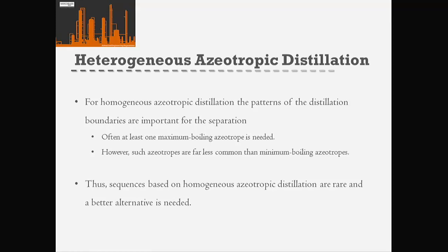So if you can see, what I've been doing is essentially increasing the difficulty of the separation as we go through. So pressure swing would be a good option if it's possible. Then if that's not possible, you might think about just adding an entrainer when no azeotropes are formed. If that's not possible, you say, okay, well, we'll allow it to be a maximum boiling azeotrope. And if that's not possible, we go, oh well, we're going to have to cope with just what we can do, okay?